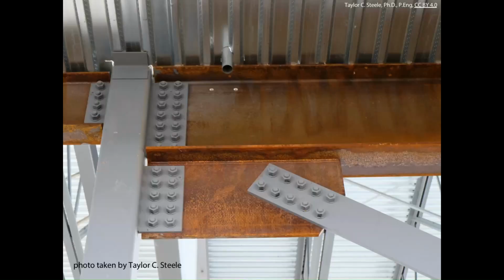How do these things come together to make certain forms and shapes? Well, in this case, we've got a picture of a bracing beam and column arrangement in that school that I showed you the other day. We've got a square HSS column. I believe that these would be 200 by 200 by something, 8 by 8 or so, maybe 10 by 10. We've got a wide flange section as the beam that's getting connected to the HSS using a flat bar connection.